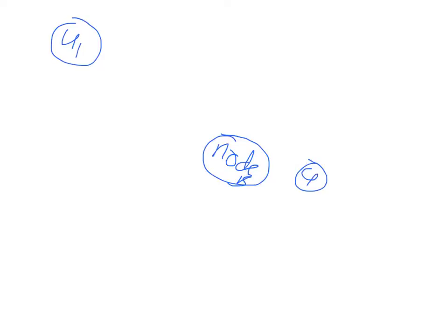I'll just do this with a diagram now. So imagine if we have a base station or a node B here, and we have one user here, and we have one user here. Now, in traditional mobile phone systems, all users transmit at the same power. So this signal is travelling this distance, D1. I'm using this notation because this shows a radio signal, and this signal is travelling D2.